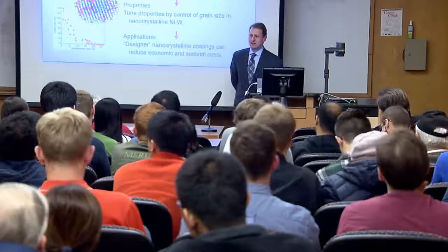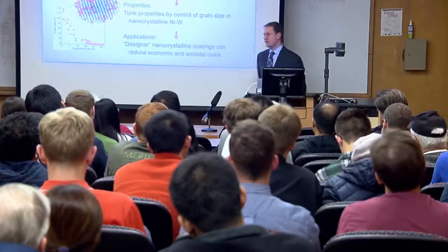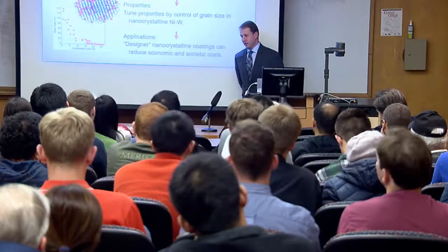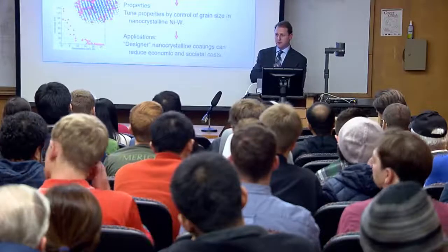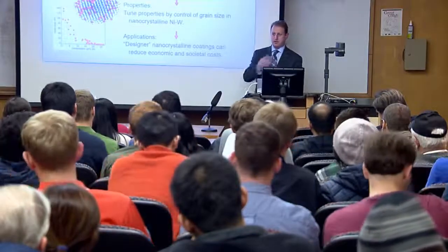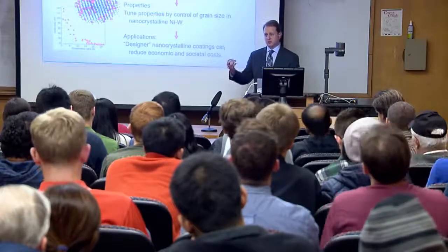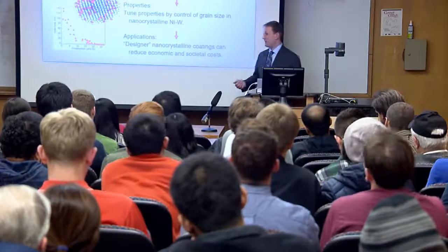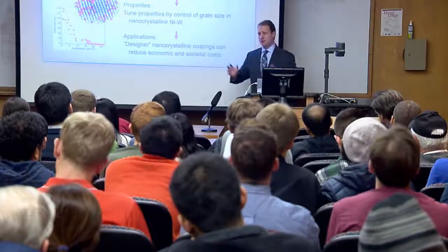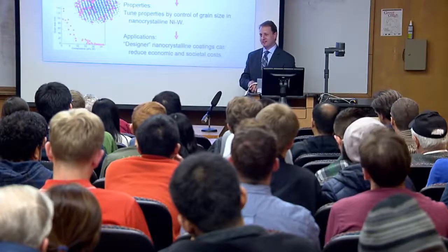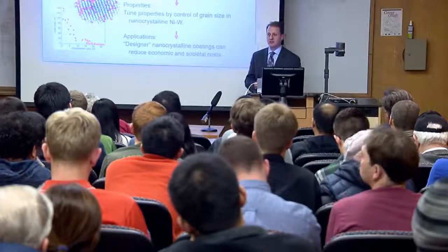I hope that you will come to the next two lectures, because your question is prescient. The primary instability in these materials is that the second phase wants to pop out. Tungsten wants to go to the grain boundary. That's an enthalpic ordering proposition. It wants to go to the grain boundary because it can achieve a degree of chemical order that it cannot in the bulk. And the competing state for nickel tungsten is an intermetallic, nickel 4 tungsten, a bulk ordered state. So you're exactly right. If I heat this up hot enough, bam, nickel 4 tungsten pops out before the grains grow. The instability is the second phase, and then the grains grow like crazy. Good question, and in fact, that's what I will talk about on Thursday: how do you deal with the second phase issue.